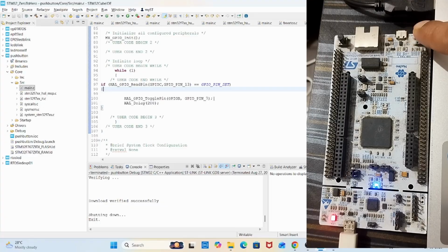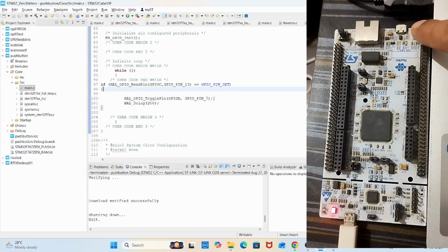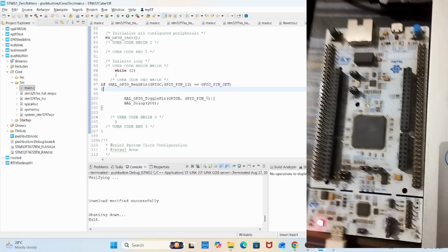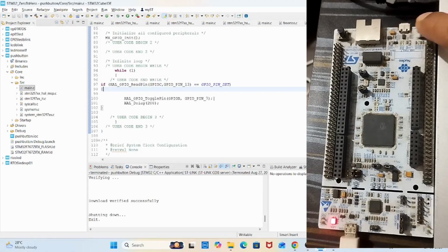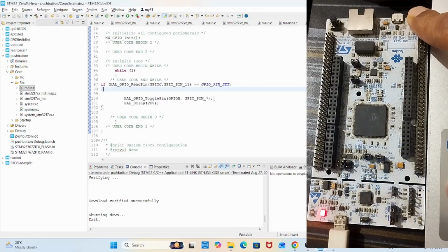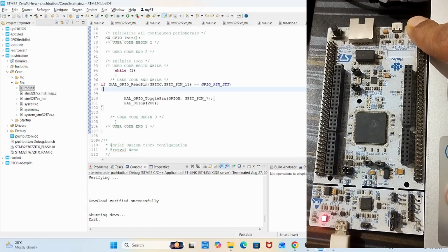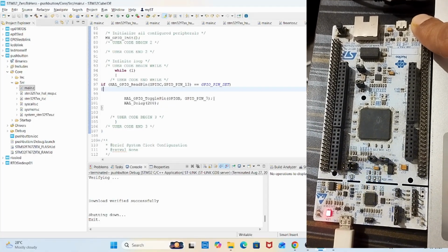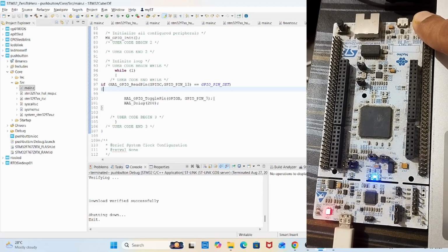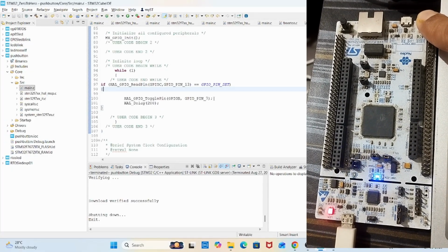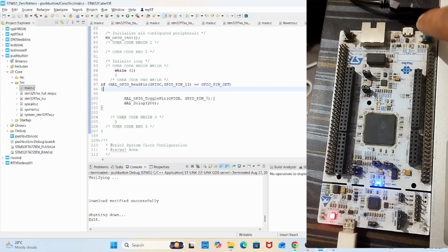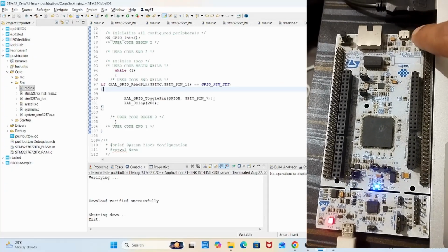You can see on, off, right? And if I keep it in this pressed condition, what happens after 200 milliseconds? Again, it is reading this status, and if the status is still set, it will toggle this LED. So you can see the LED blinking with an interval of 200 milliseconds. But this is how your controller will read this switch, or read the push button.